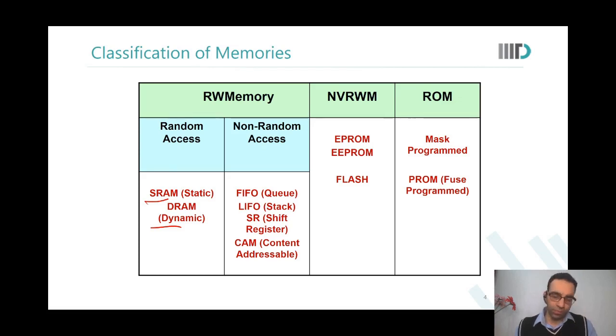Great. So see, typically when you talk of a memory, you would give an address location, and you would want to find out what is written on that particular address. A CAM is something different. CAM does not know what the address is. CAM knows what the content is. So you search for the content, and that leads you to the address. And then from that address, you may do further operations.